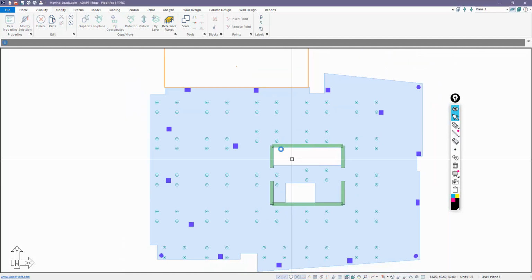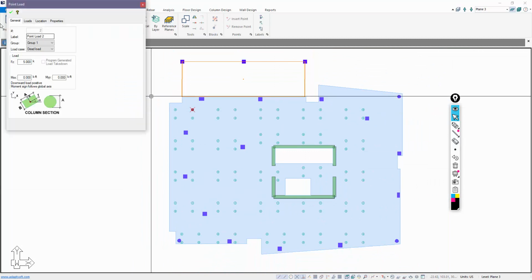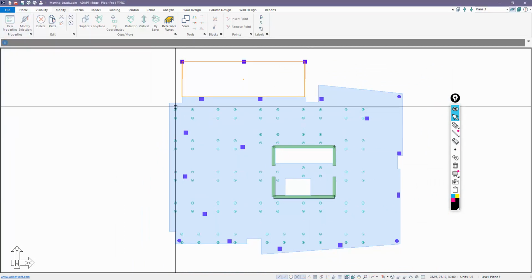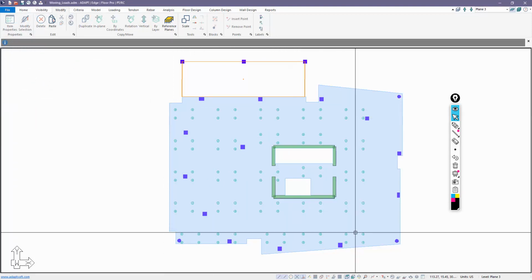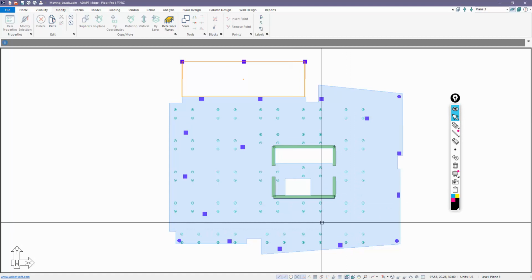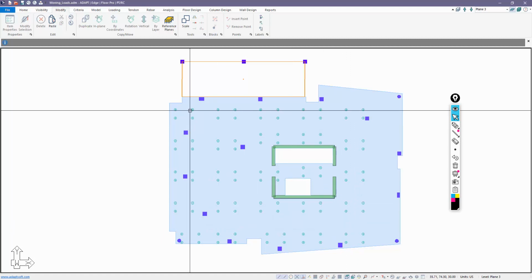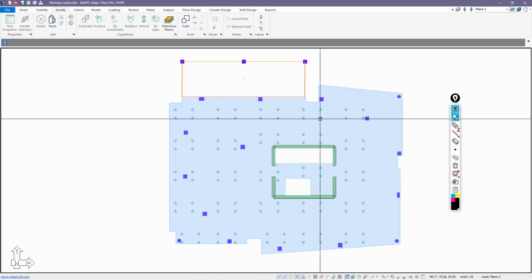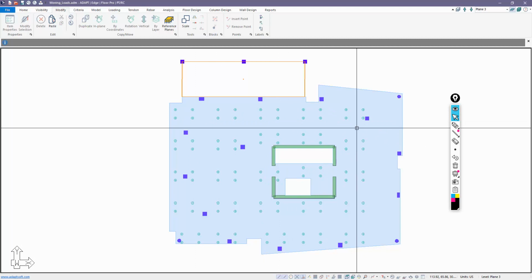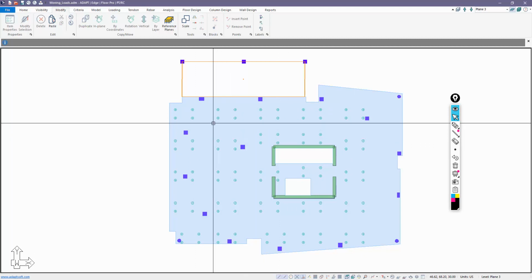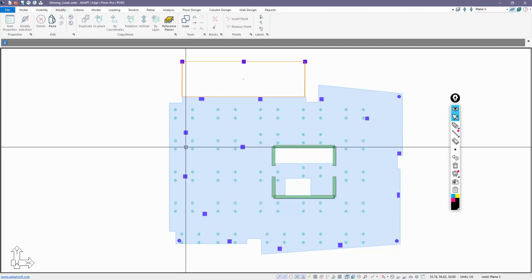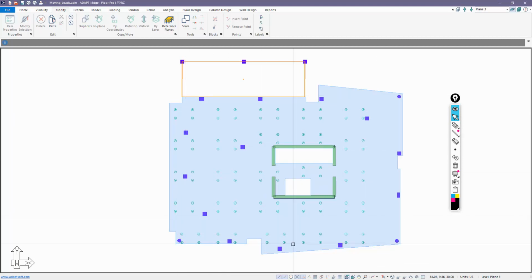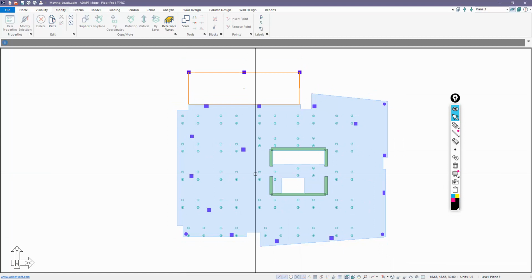Okay. Now, because all of these are currently represented as dead loads, each one of these has to have its own unique load case. Otherwise, they would be applied at the same time, and we need to be able to envelope the results based on these load sets being positioned individually on the slab. So we have 5 times 5, we have 25 unique sets of loads.